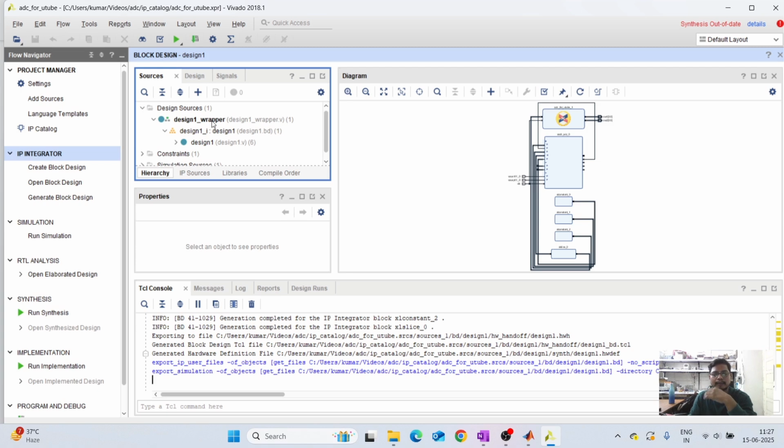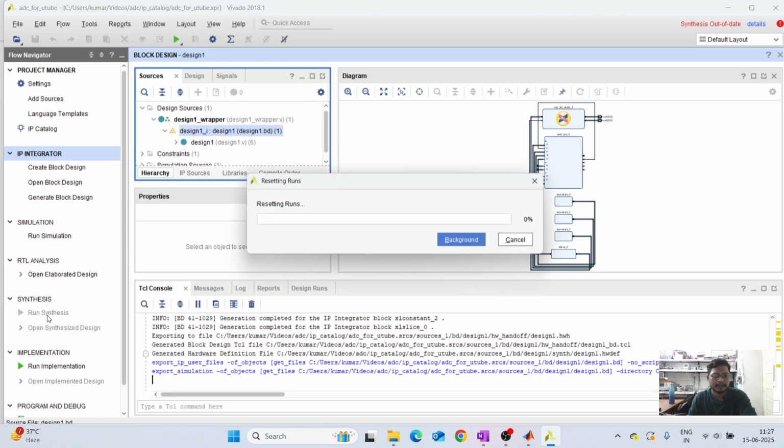You can see the parent, whatever Verilog files or block design we have made, this one is the parent. So everything is completed. We have created the .v file and created the HDL wrapper. Now save it, Control S, and again I am trying synthesis.